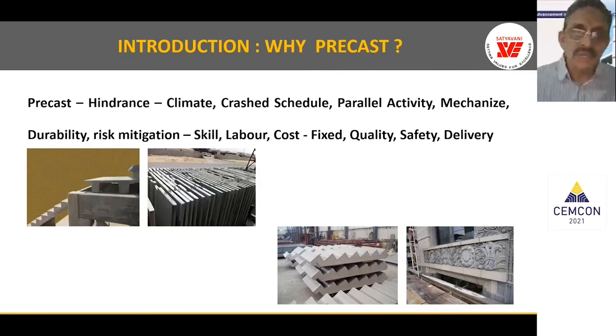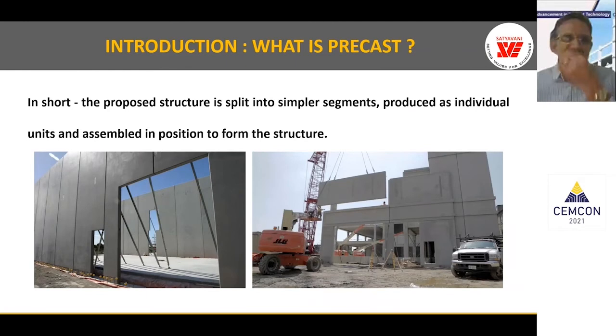Also, I have chosen precast because of the better quality and reduced carbonation in concrete, and the risk mitigation like skill and labor constraints, and also cost constraints, because escalation in cost is bound to happen when we do large scale projects because of the sudden spike in the demand for material. So through precast, we can have fixed cost delivery of the project, enhanced quality, better safety management and assured delivery. So these are all the reasons why we have to choose precast in building construction.